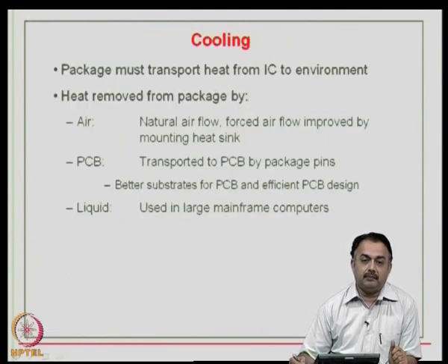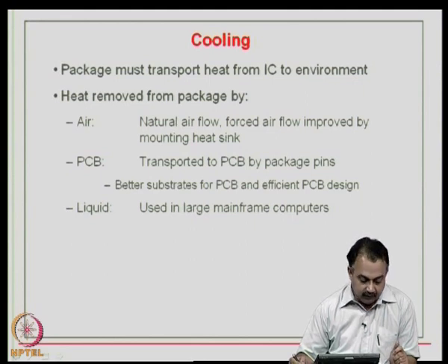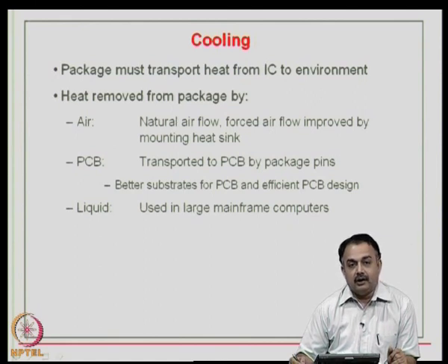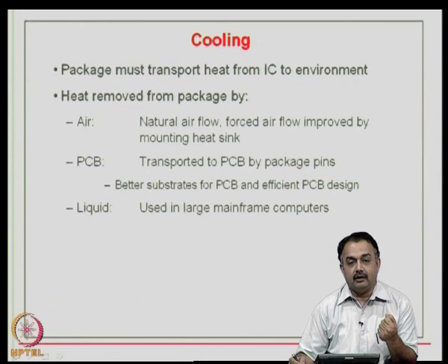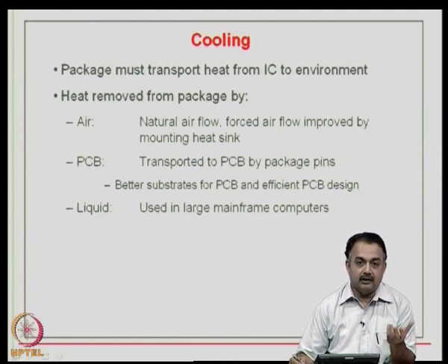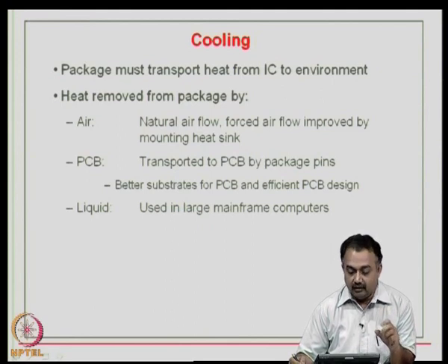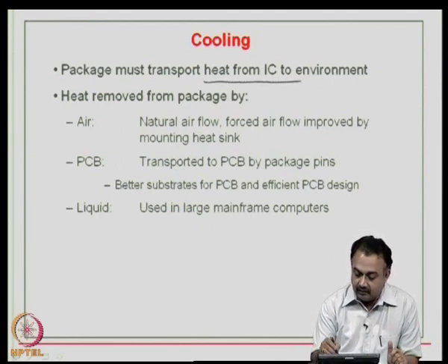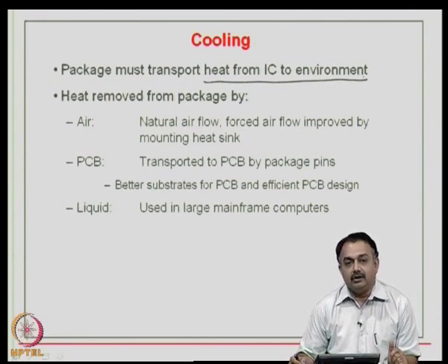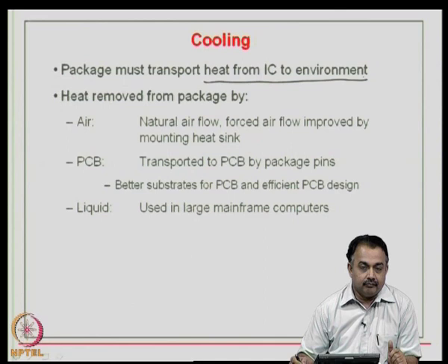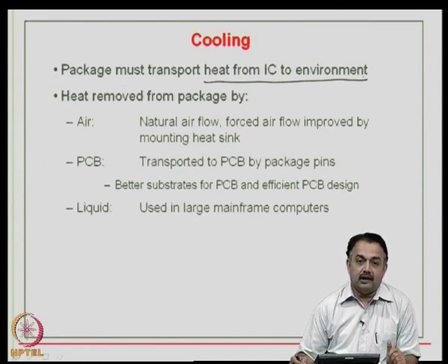Another important aspect when you look at packages would be the cooling phenomenon. When a die is packaged and connected to the external world by means of a lead frame structure or a solder ball arrangement in an area array format, whatever be the case, the package must transport heat from the core die to the environment. So, heat from the IC to the environment should be removed faster, quicker, and effectively,